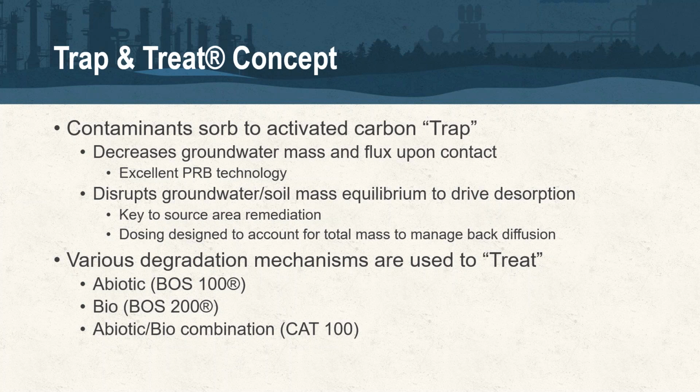The one comment that I'll make, and I'll probably make it several times here in the presentation, is that if you're trying to meet a soil standard out on your site, we have to really look at that, look at the contaminants, look at KOCs, FOCs, because obviously different contaminants are going to come off easier than others. I know it's not the focus of this presentation, but if you've got a diesel site, for example, when you have a diesel soil goal, diesel range organics can be difficult to desorb off of soil. And obviously the soil type is going to play into that as well.